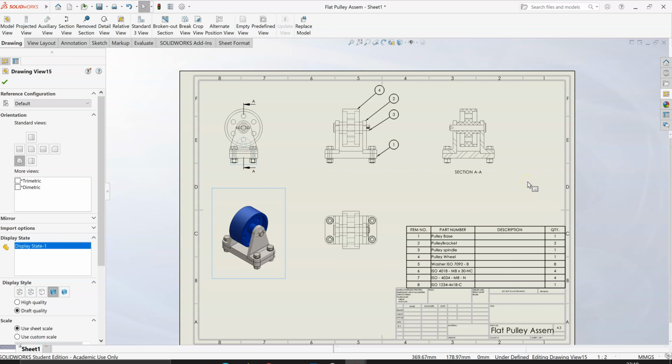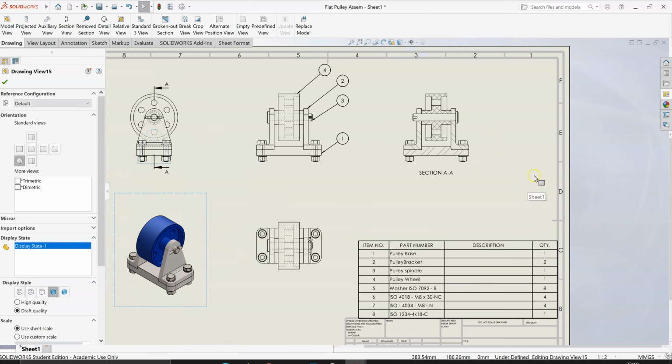The other thing that you may sometimes see on assembly drawings is some dimensions. Now, typically you wouldn't dimension parts, so I wouldn't put in a diameter 12 on this spindle, for example, because there will be a separate drawing of that spindle on its own with the detailed dimensions for that. But what you may see on the assembly view is some overall dimensions of the finished assembly as it's all fit together.